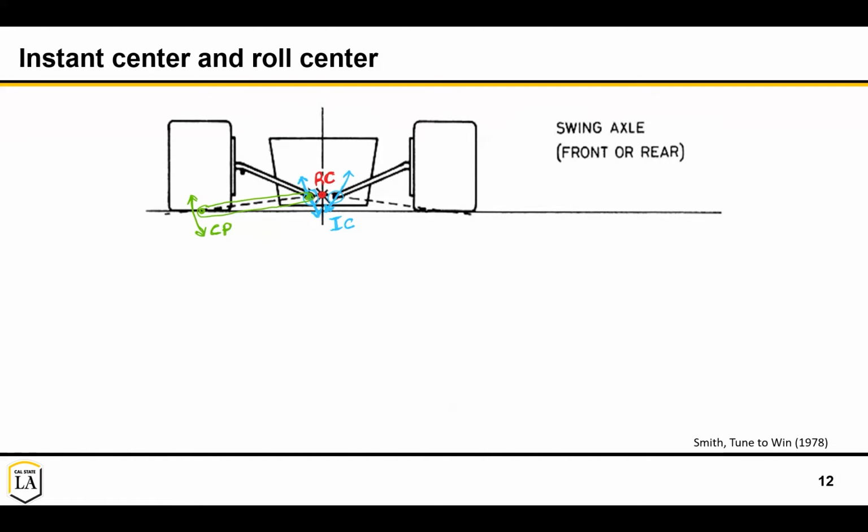And so when designing the roll center, we usually think about the height of the roll center. It can move around laterally, and so that's one thing to keep in mind as your wheels travel. But first, let's think about it in the static case. So the higher this roll center is, if it gets all the way up to the center of gravity, the difference between the roll center and the CG would be 0. And that difference we call the roll moment, because the mass times acceleration term times the moment arm to the roll center is what's going to cause it to roll.